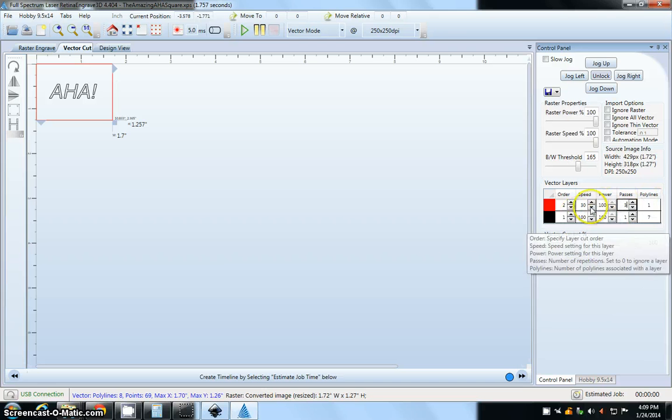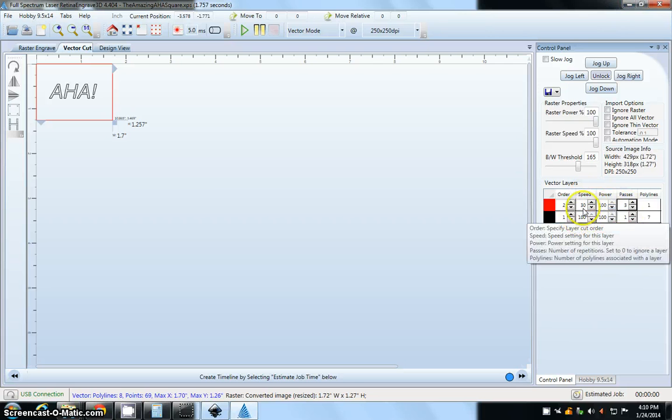These aren't arbitrary, randomly chosen amounts. I've done this a few times. There's a file, and I'll show that in just a second, that has some known settings. So this section, that black section where I'm going to engrave, I don't want it to cut, so I'm going to keep the speed way high. I'm going to change the power way down. If you don't know your material and you're not quite sure what's going on, high speed, low power are good rules of thumb.